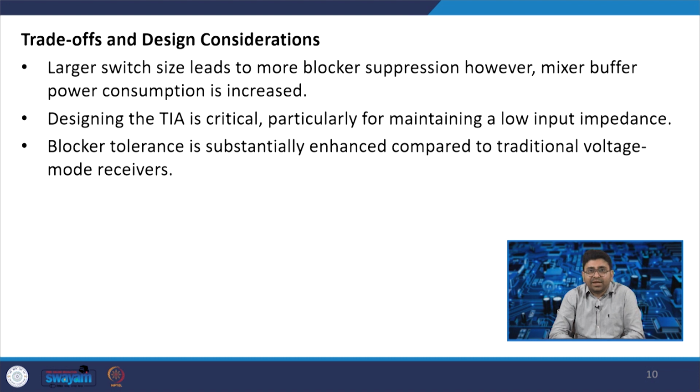Trade-offs and design considerations. A larger switch size leads to more blocker suppression. However, mixer buffer power consumption is increased. So, designing a TIA is critical, particularly for maintaining a low input impedance, and blocker tolerance is substantially enhanced compared to the traditional voltage mode receiver.